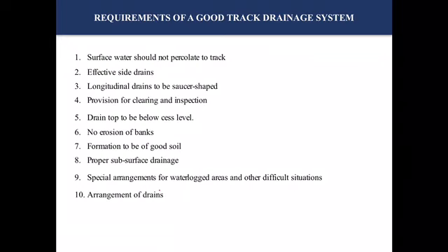And the surface water from the adjoining land, which can be agricultural land or any lake which is present, should not enter into the track section. And also the longitudinal drains should have proper sufficient capacity, and the longitudinal slope has to be maintained properly so that it will effectively carry away all the possible surface water.